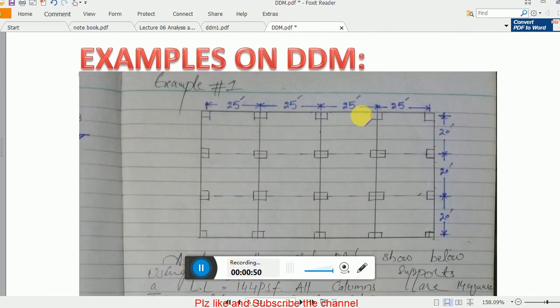We have this example, and remember there are no edge beams. Edge beams are the perimeter beams which are provided at the perimeter of the slab system, and we have no interior beams. Already we covered this example by the ACI moment coefficient method. But in that case we have beams, and when you have beams you can analyze that slab system by DDM as well, but the moment distribution coefficients will be different, and that kind of slab system is a little bit complicated,